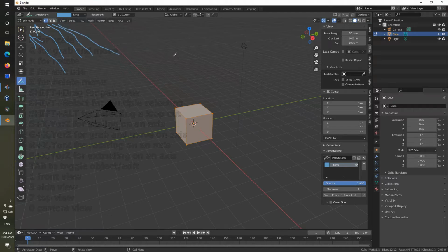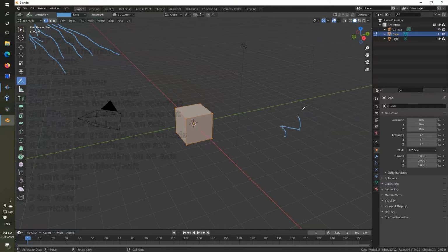Then you've got your point, edge and face select. You need to check those if things are not working. That side menu, N toggles the side menu, and once again in solid view, just in case you hit the Z key on your keyboard, and accidentally bring up the menu to change your render view.